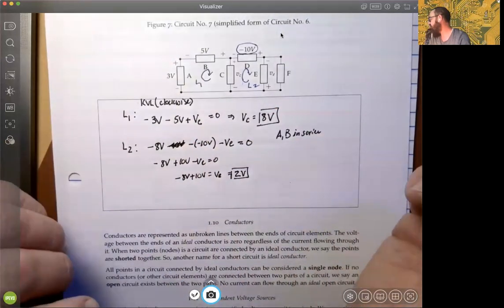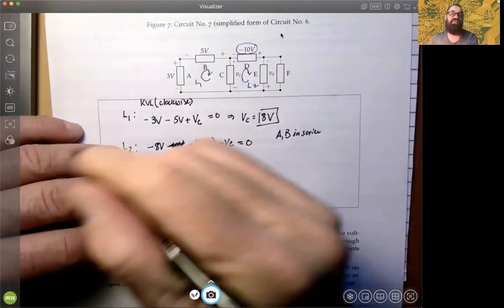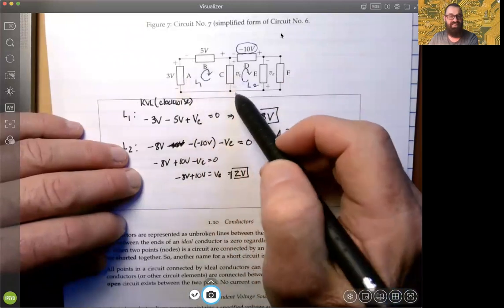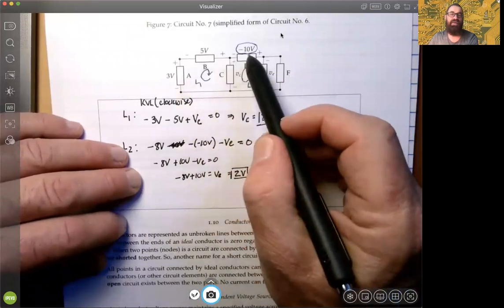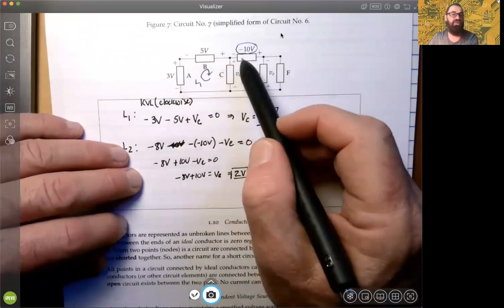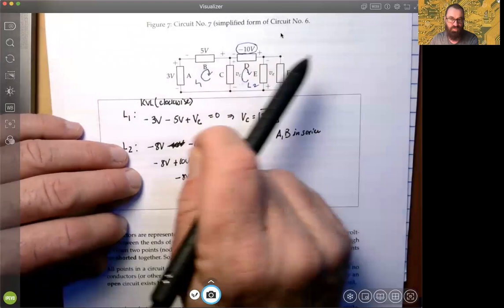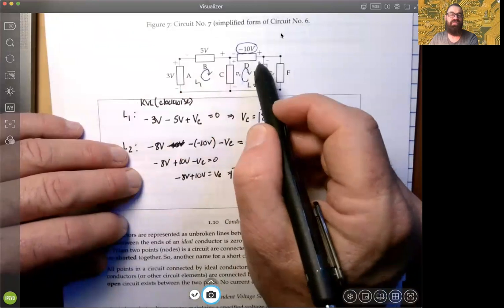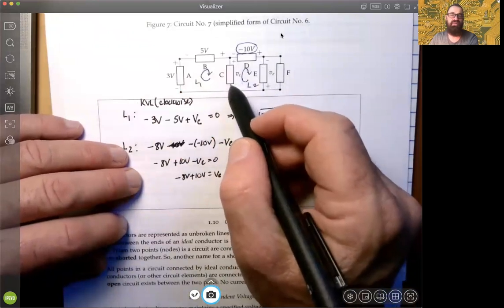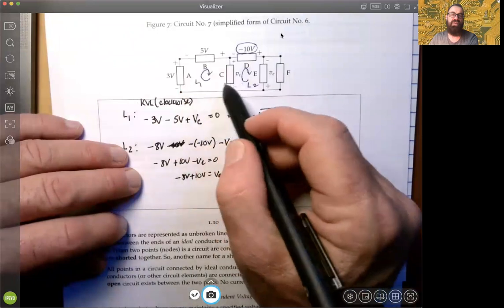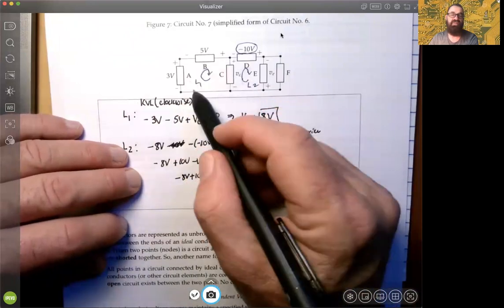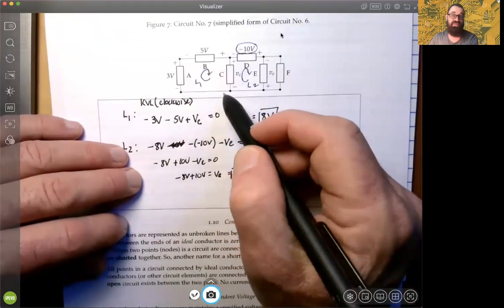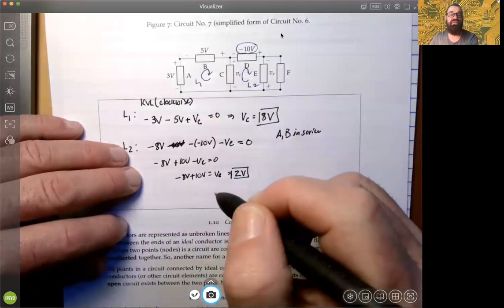And then you might ask the question, well, wait a second, how come you didn't add C, right? Well, because B does not necessarily have to go into C. See there, it has a bypass, it has another exit. There can be no exits in series. You must be forced into this path, right? So the fact that there's a branch here, another way to flow, C cannot be in series, okay? Same thing with A. E could come into A as well as C coming to A. So there's no guarantee you're coming into A exclusively through C, all right? So only A and B are in series.